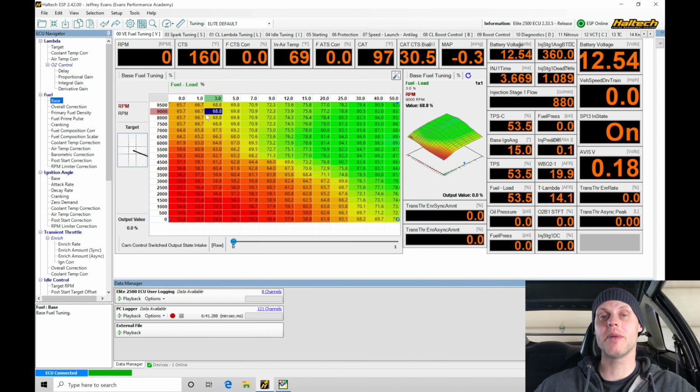started. Welcome back to our live training with our K24 swapped EG Civic running Haltech Elite 2500. In the last video, we got our engine fired up, we checked the timing with a timing light, we built a TDC offset trigger angle table so that our timing was tracking as we were going up in engine RPM, our timing was consistent. We checked out getting our fuel sorted out using our fuel correction and scalar amounts based on our fixed ethanol content we're telling the Haltech that we're running, which is roughly 70%. We got all of the fuel delivery sorted out.